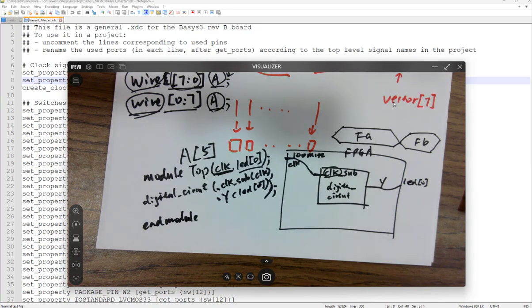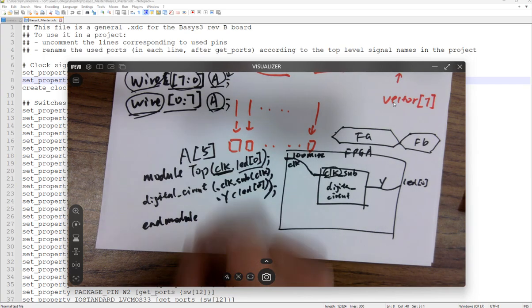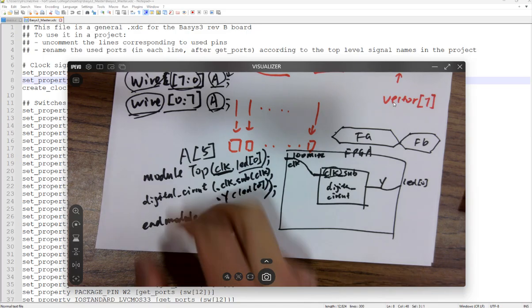You don't need to assign signals to it. If you want to make it complicated, you can definitely write variable coding here to modify or control the behavior of the clocks and everything. You can even add an always block over here. But at the FPGA top, you can see I'm actually just making physical connections. Instead of using my hand to manually make the connections with wires, I just code it up.